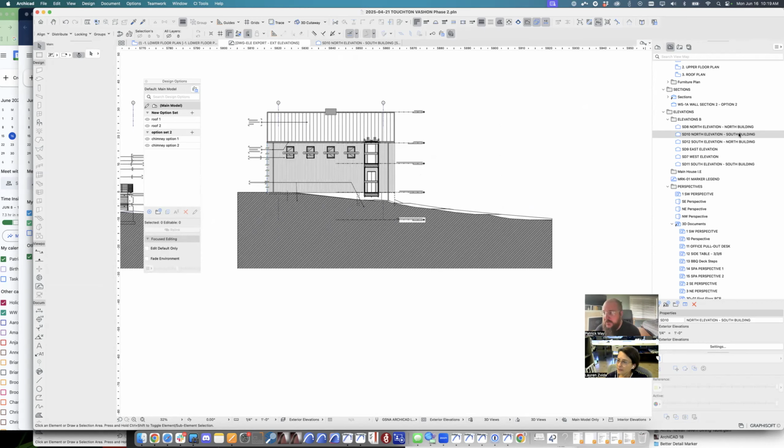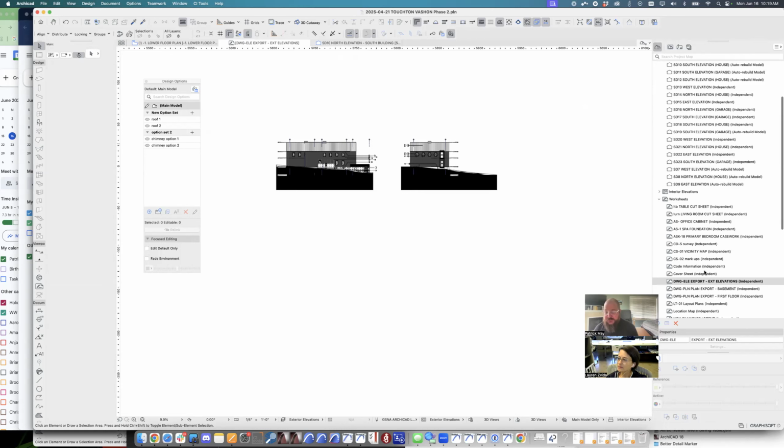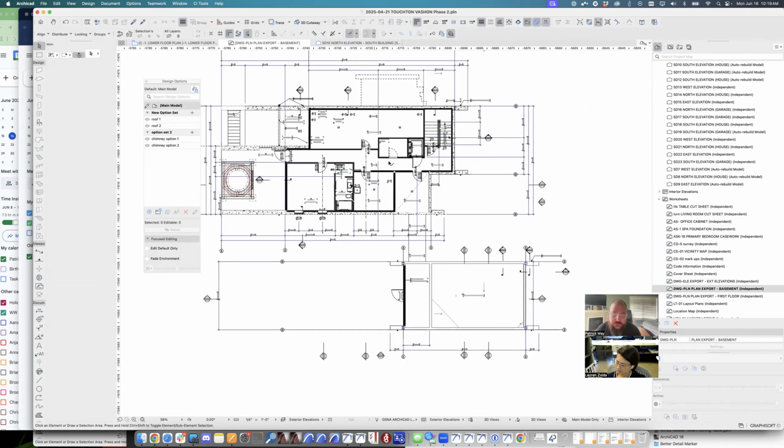Yeah, so from here it's just a save as. Okay, so that's plans, sections, and elevations. You're going to basically create these worksheets and copy and paste all of the views. For the plans, you could have the basement plan as a base plan, and the RCP as a plan. I don't know if you're using the 3D document and floor plan as your RCP method. I am not, actually. It's just a work view that I have. That makes it quite a bit easier.